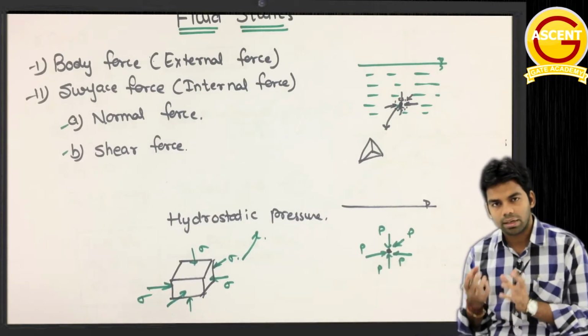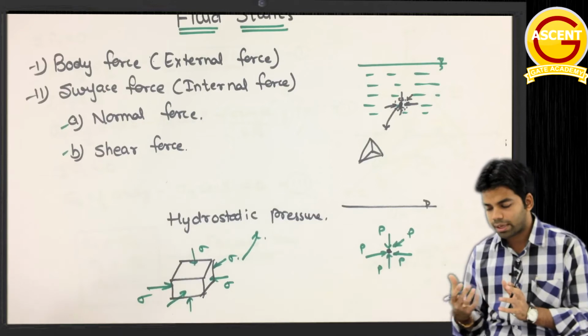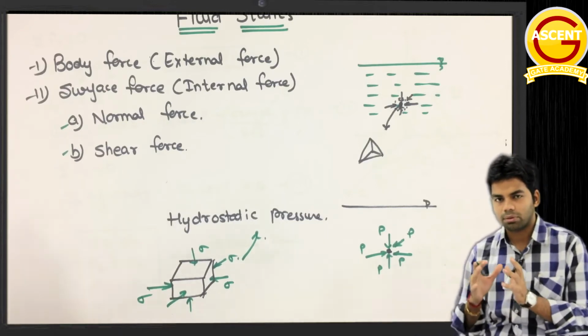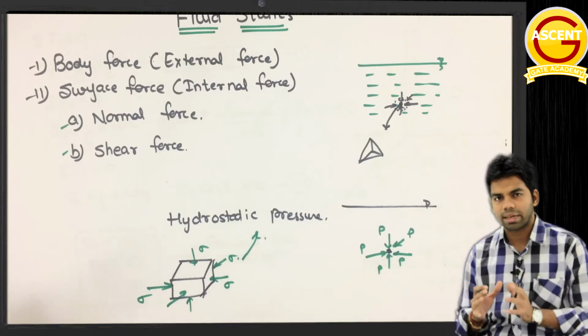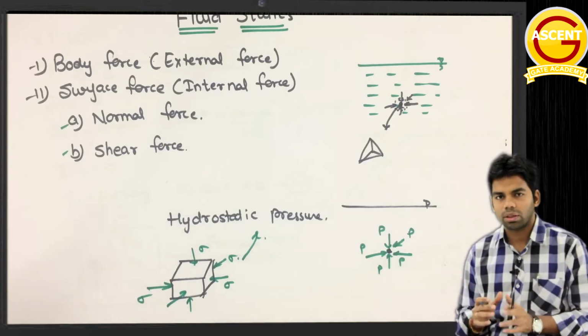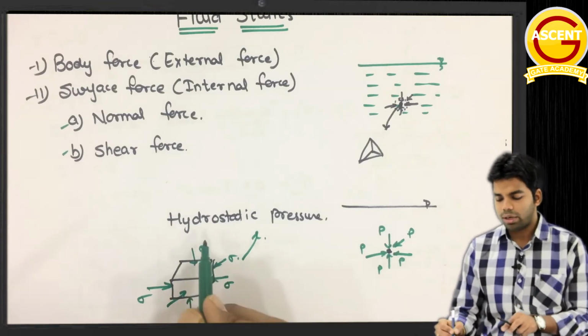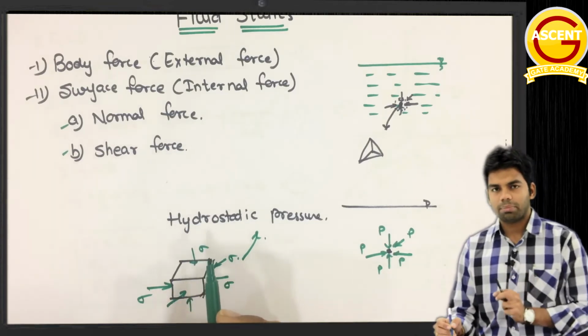If we have a fluid element inside a fluid at rest, then the forces acting from all directions on that particular fluid element will be the same. Not the forces, the stresses, or the pressure acting from all directions, is the same. This is called Pascal's law, and that pressure is called the hydrostatic pressure.